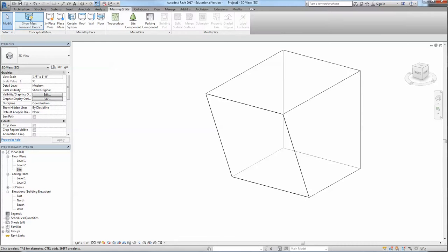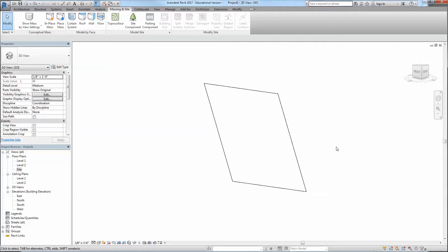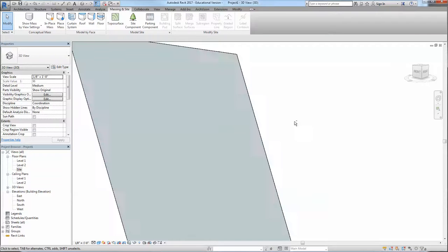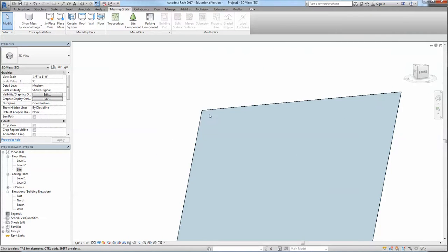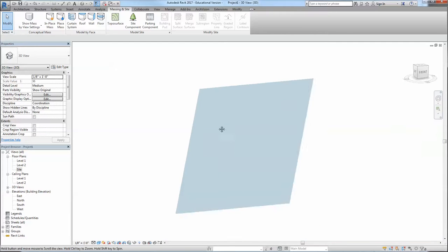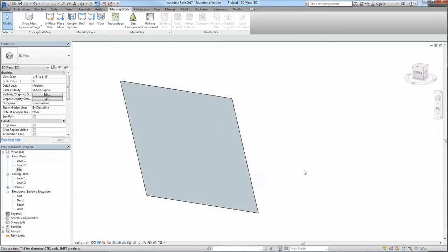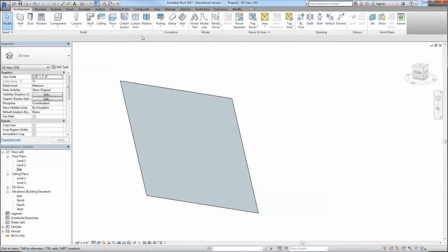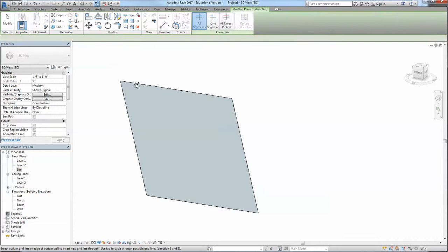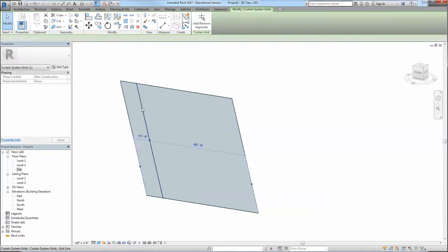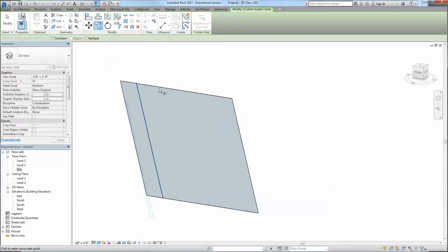We can go to massing inside and turn off the mass, and go to shaded view to see that there's actually a normal glass panel. Okay, so at this point I'm not going to go into details because they're exactly the details we talked about last class. So I'm going to go very fast. Which means what? We can create our curtain grids, and we can start placing our curtain grids any way we want. We can obviously copy them, and start aligning them at different lengths.